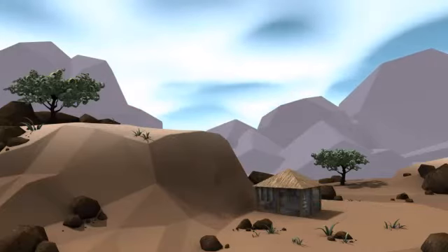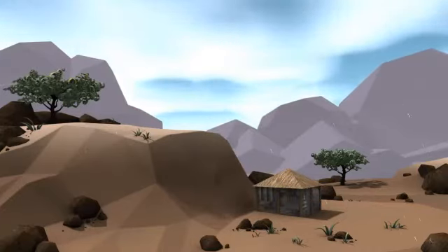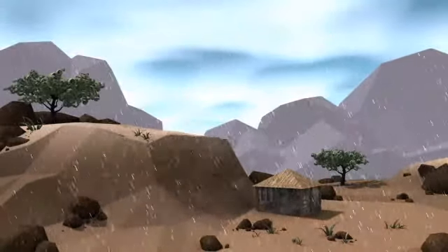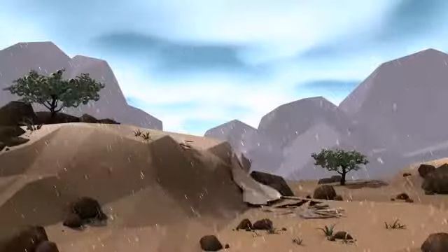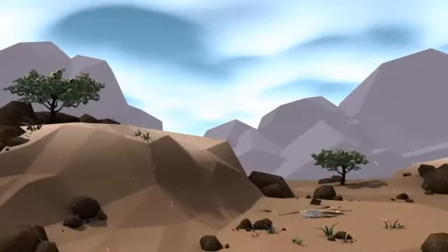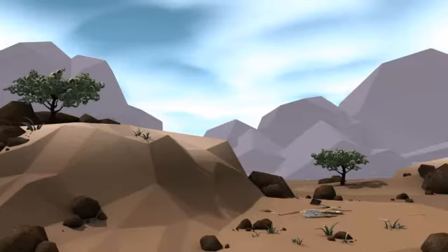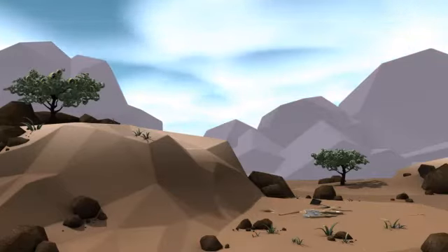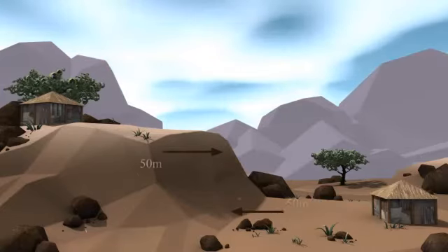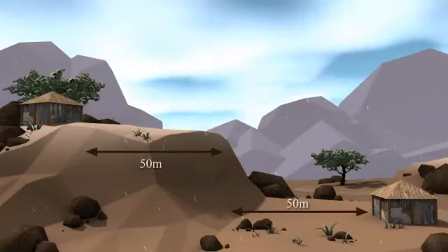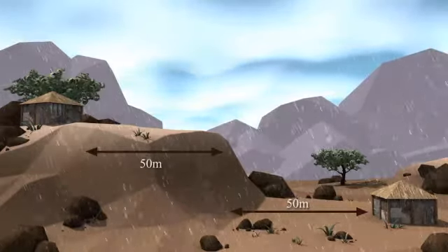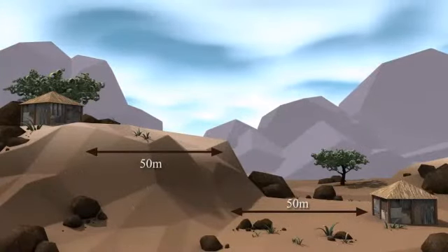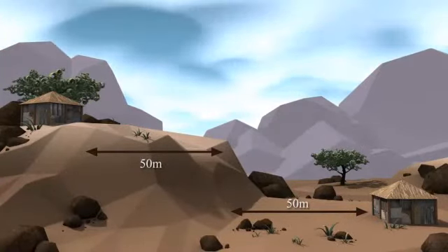It is equally risky to have a shelter located on the bottom of an unstable hill. The major risk is associated with collapse of the shelter due to the mass of land or rocks that may slide down the hill with the landslide. The shelter may thereby be severely damaged. When building a shelter located on higher ground or at the bottom of a hill, leave a safe distance from the edge and the bottom of the hill. Recommended practice is a minimum of 50 meters. This will create a safe area in between the shelter and the unstable hill, minimizing the risk of the shelter to potential landslides.